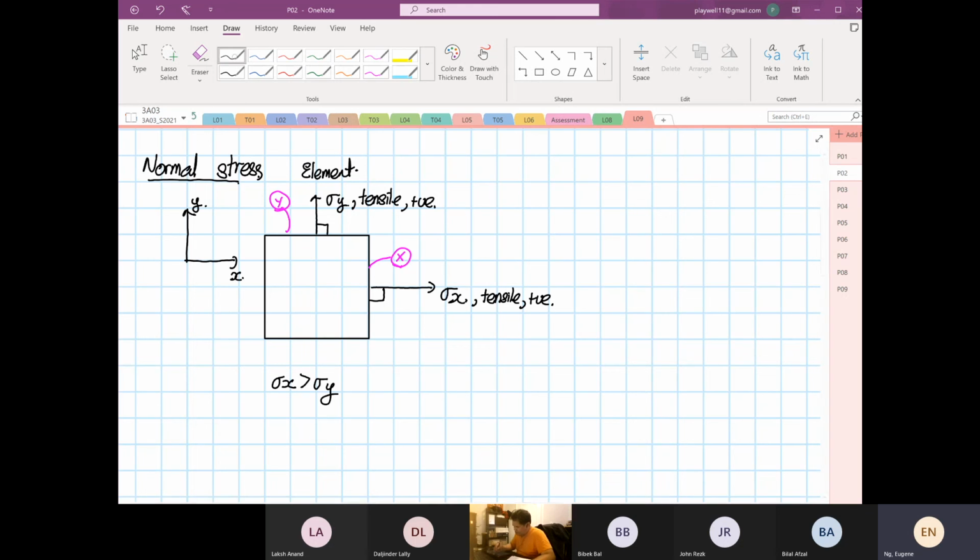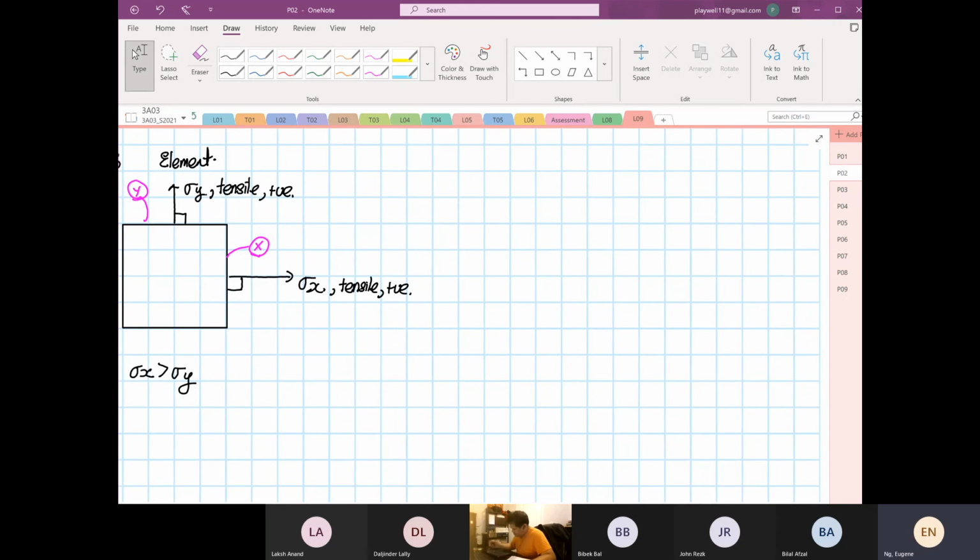By the side I'm going to draw a Mohr circle. Over here this is the Mohr circle. The x-axis over here is our normal stress, and on the vertical, this is our shearing stress. I want you to have a good habit to draw that the shearing stress generates clockwise rotation of the element.